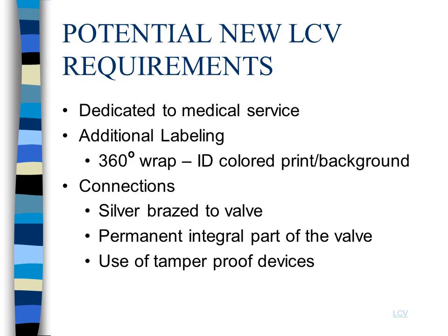What happened was the driver inadvertently delivered nitrogen to an oxygen facility. Numerous people became ill, a few died. That's why the use of tamper-proof devices is a requirement.